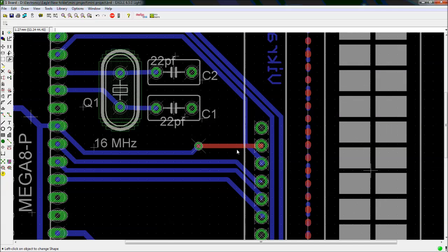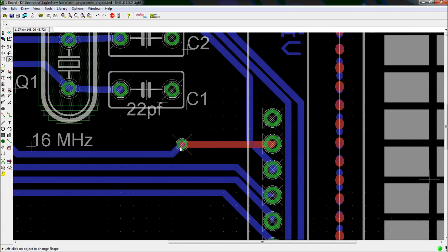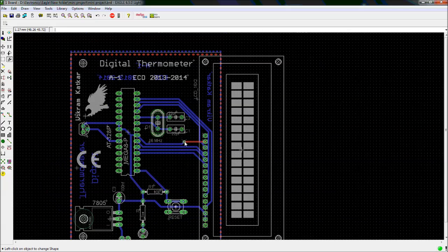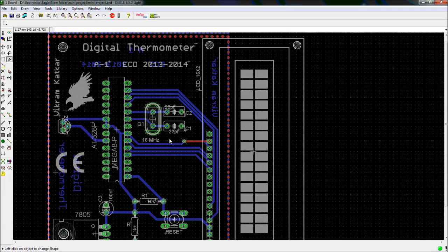This shows that up till this point the wire is at the bottom, and then from this point to this point we are connected using an overhead wire, or you can say a jumper, or you can go to a double side PCB. If you are having a 2-layer copper sheet, then you can go for it.